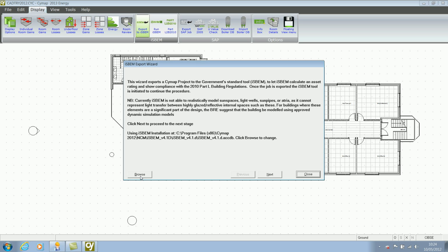But a word of warning, if you do it here in the energy program, you would need to go back to the building program and adjust your template profiles to take into consideration your building type so that the activity levels and vent status of each space can be applied, otherwise it won't work.